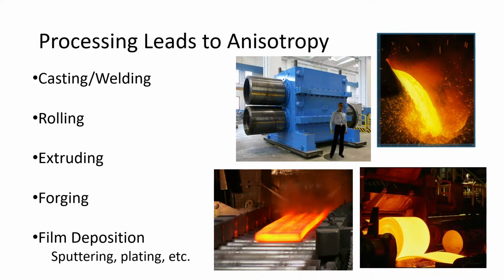Now, it's not always straightforward. We think of slip planes and how this works, and the slip planes are lining up in the standard Schmid example with the zinc single crystal, where you pull the rod and the planes rotate, and you can see them rotate with the slip lines. And sometimes that explains everything. But sometimes if you sprinkle in a little bit of extra alloying element, even a few percent of something, then things behave differently.